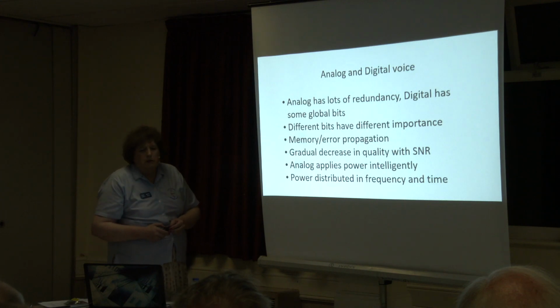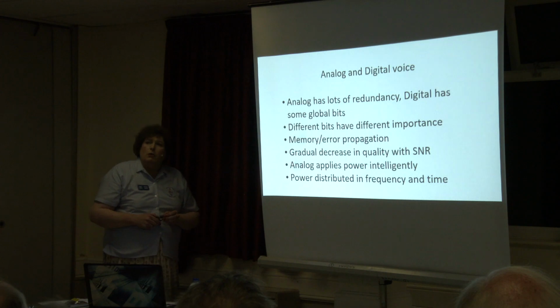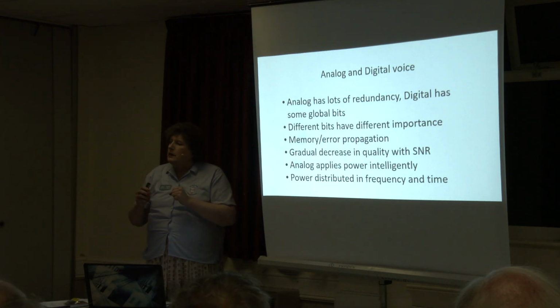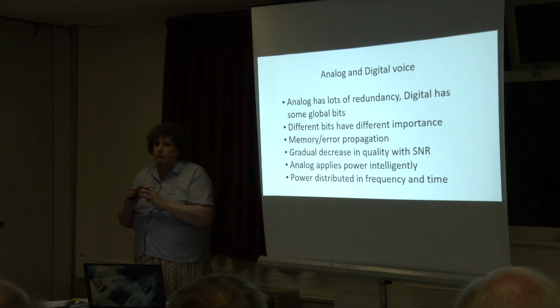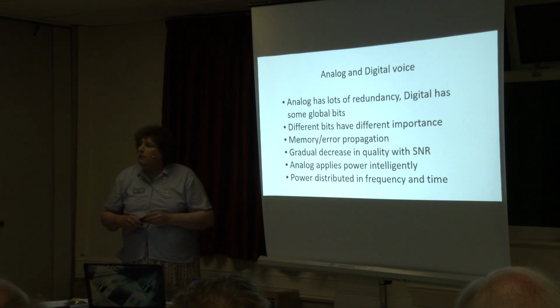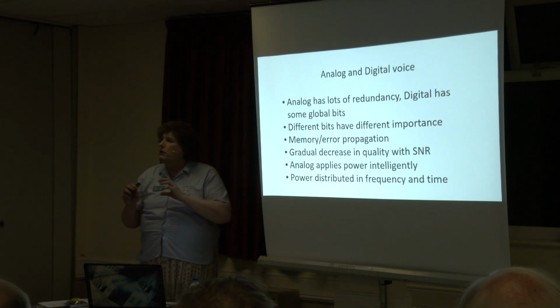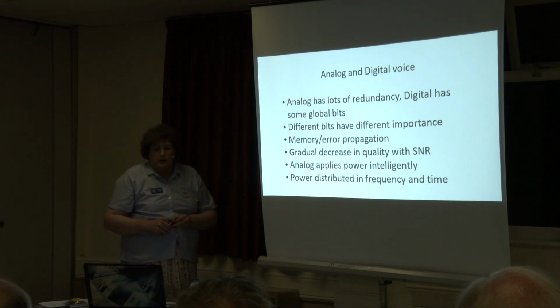With normal voice, there is a gradual decrease in the quality of signal to noise. The more noise on the band you get, the less intelligible the actual audio signal becomes. So the more mush you get, the harder and harder, and the more interference, maybe from your VDSL or whatever, you also have great difficulty in being able to understand the voice.